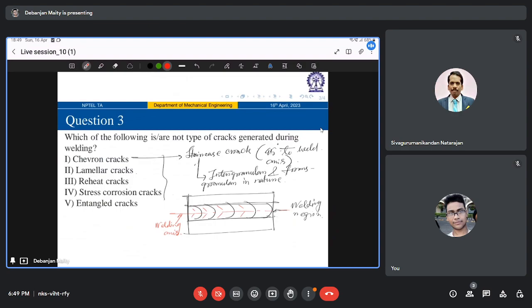Now, this liquefaction cracking is seen to occur in the high temperature region of the heat affected zone. You can see it in different kinds of steel also, like austenitic stainless steel, heat treatable steel, and also in aluminum and nickel based alloys. So this kind of cracking can be particularly, what should I say, dramatic in the heat affected zone of cast irons.